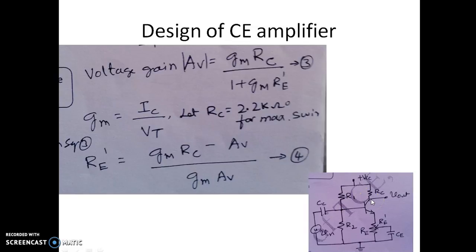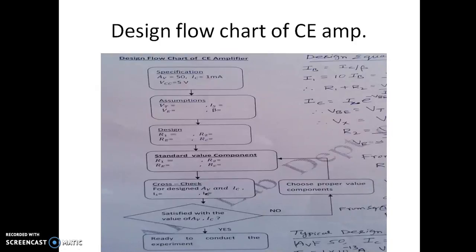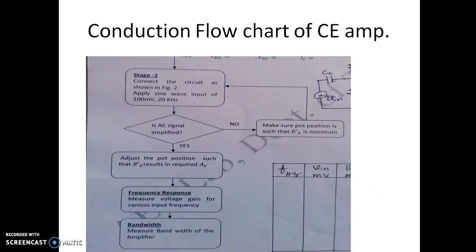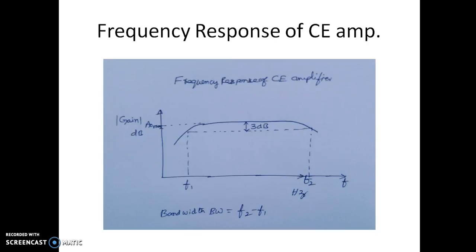Measure it over here, it's an amplified version, and you change the frequency of the signal and verify the amplitude. The amplitude will keep reducing as you increase the frequency. You can do it frequency by frequency, or you can go for a network analyzer where you'll be sweeping the frequency so that you'll get the graph directly.